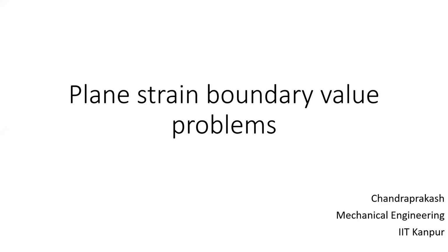Welcome everyone to the fourth lecture. In this lecture we will see what these special kinds of boundary value problems are, and we will start off with the plane strain boundary value problems. We'll see how the formulation works, how the boundary conditions get simplified, how the domain equations also get simplified, and what are the ways by which we can solve it.